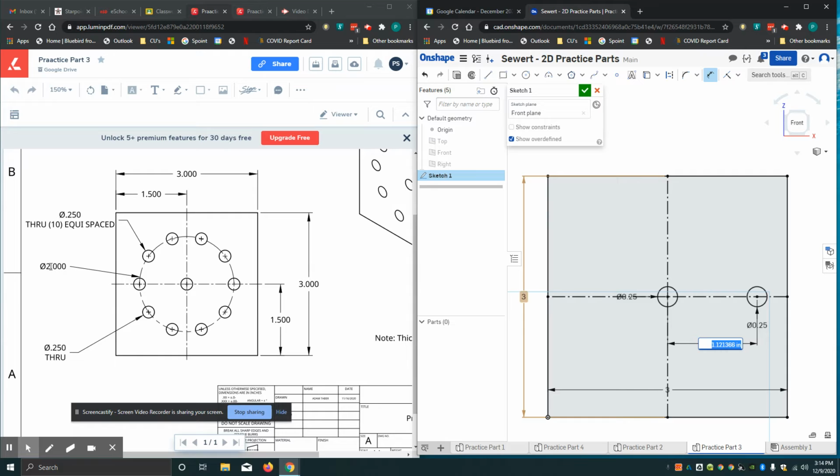The radius is going to be from here to here. So I'm working with radius over here. So I've got to take 2 and divide that in half, and I'll get 1, and I'll hit enter. And there it is. My circle has turned black.